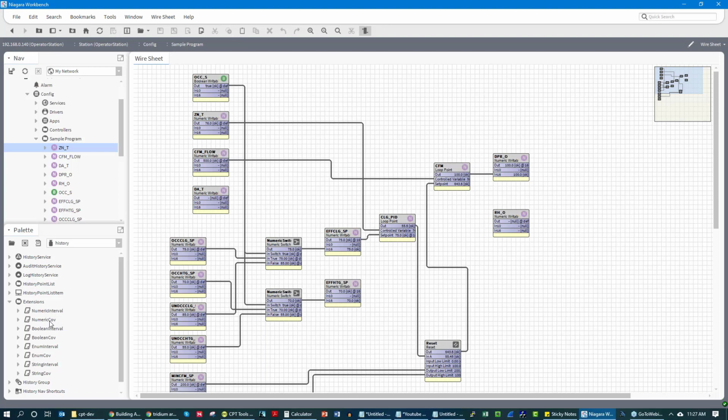We would do 15-minute intervals, and the reason why is if you think about a space, your average air changes in a space are 4 air changes an hour. So 4 divided into 60 is 15, right? So that's where that 15-minute interval came from, is, hey, we're going to do that. Also, some folks will argue that the 15-minute interval came because of calculated capacity of trend storage, but most of the time it was based on the space changes or the airflow change rates.